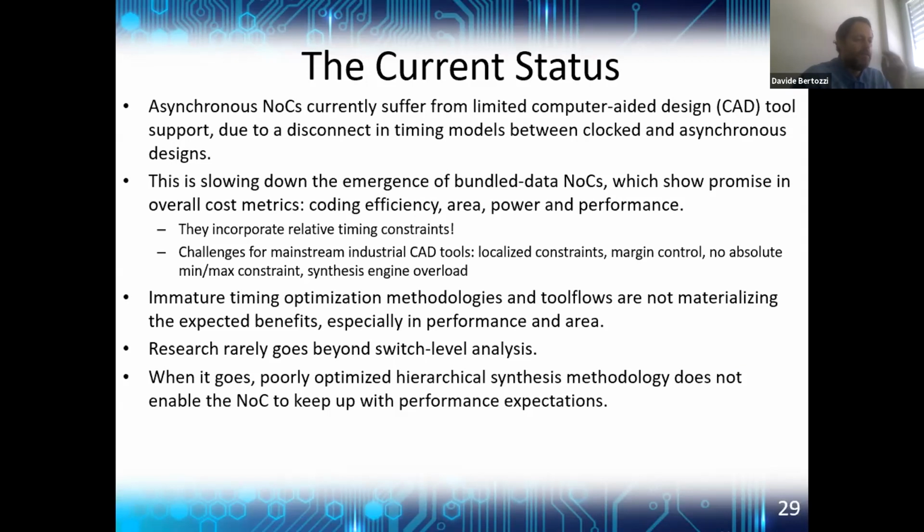And this is a disconnect in the timing models for mainstream industrial CAD tools for a number of reasons. Unlike synchronous timing, these constraints are localized. There is no global timing constraint. Okay? There are only local timing constraints. And unbalanced pipeline stages should be allowed to collectively interact with their own matched local delay. Moreover, fulfilling relative timing constraints is not enough. You need to not over-design the constraint. For instance, the request signal shouldn't arrive too late with respect to the data path line to match, because this directly translates into latency and throughput limitations.